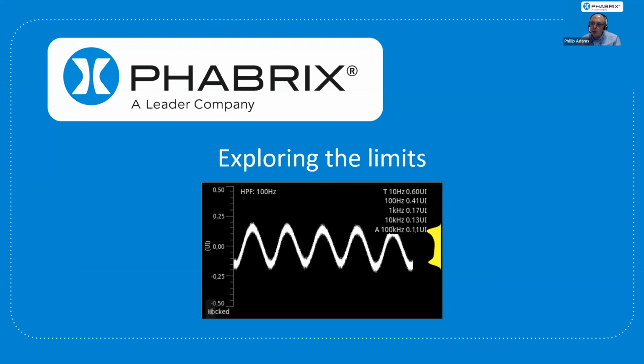We created an advanced stress tool set to go with the QX range as an option. A lot of it was to do with testing with MACOM and Semtech and TI. We worked with all those companies. We asked them what they wanted, and they advised us as to what they would like, and we put a whole lot of tests together. These are quite advanced, so they're for more advanced testing. So normally you'll be looking at your eye pattern, you'll be looking at your jitter, and you'll just be checking that you meet spec, etc. as per the rest of this document. But we have some much more advanced tools. You can see here we're inserting sinusoidal jitter at a particular frequency, and you can see that here now.